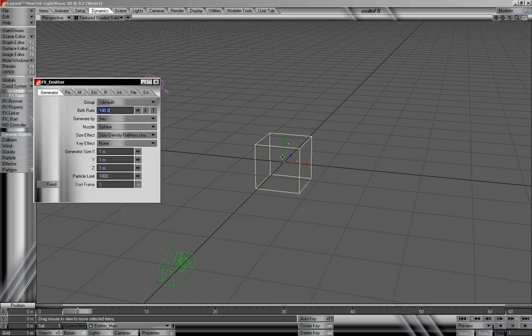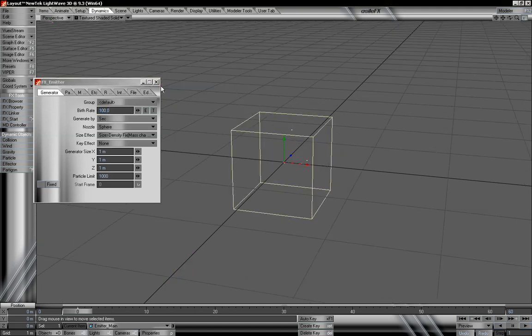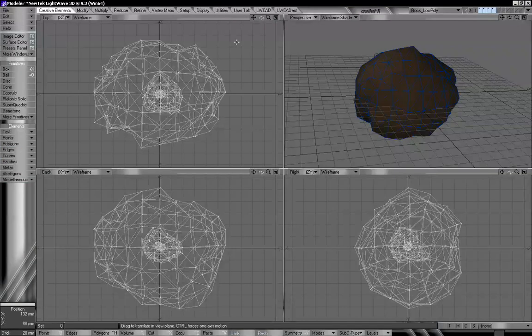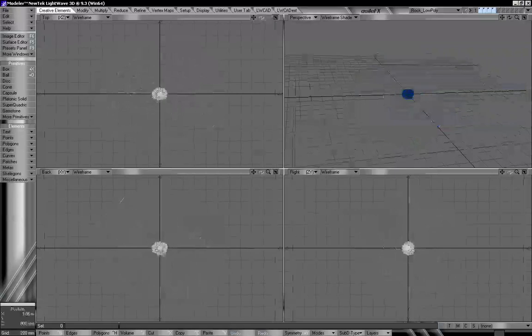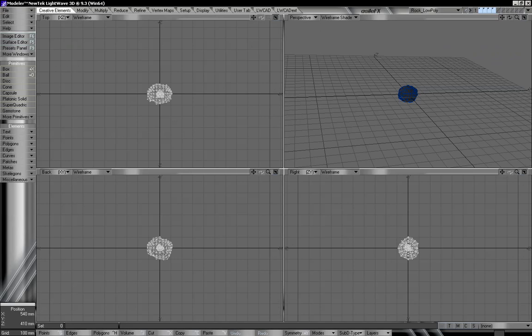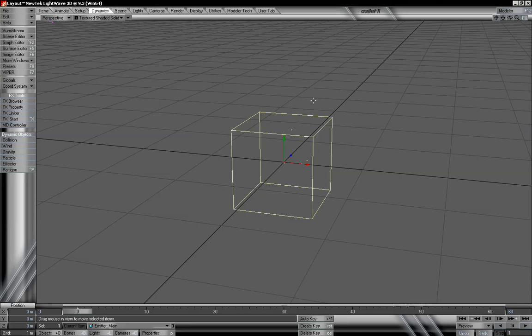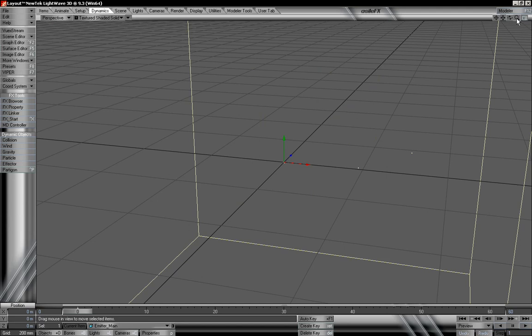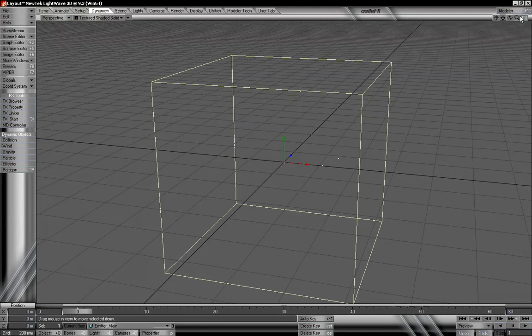And I need to take a look at our scale in relation to our objects. So I'm going to close out our properties. We're going to go back into Modeler, and we need to take a look at the size of our largest object. And it looks like our largest object is around 200 millimeters. So we'll switch back to layout, and now we need to keep that in mind while we're working on this specific item. So I am going to use the left bracket key to decrease the grid size.